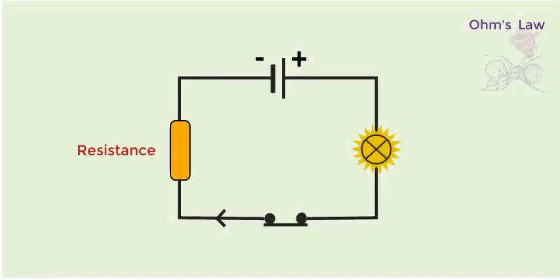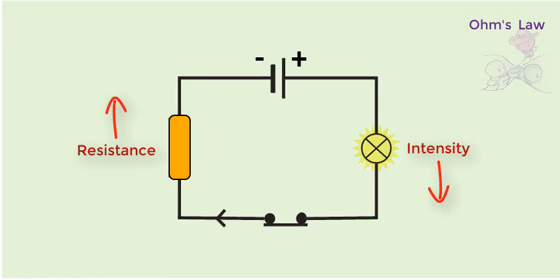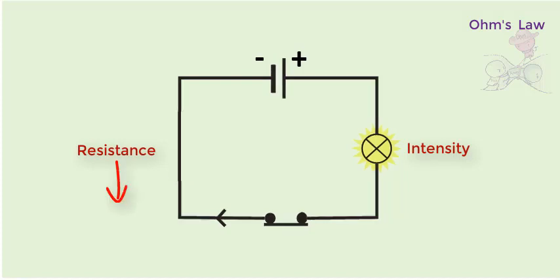It is therefore the resistance that determines the intensity and not the other way around. In the vehicle, the voltage is usually that of the battery. When the voltage remains constant, if the resistance increases, the intensity is reduced. In the same way, when the resistance is reduced, the intensity increases. The resistance of the component depends on its physical specification.